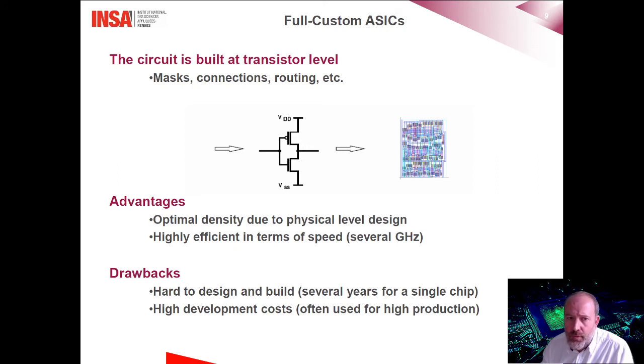The first family is the full custom technology. In this type of circuit, the design is performed at transistor level. That is to say that designers have access to the transistor architecture itself. They can directly design the transistors and the connections between them using what we call masks.